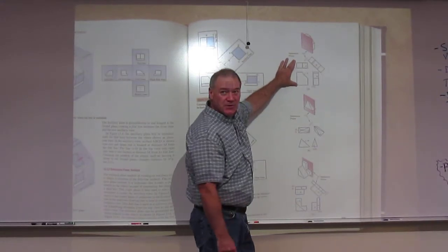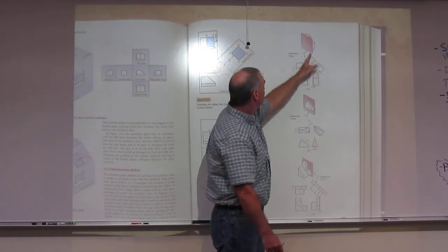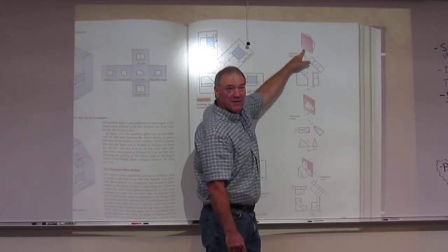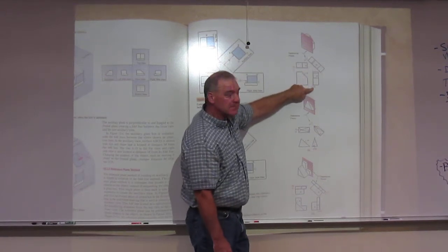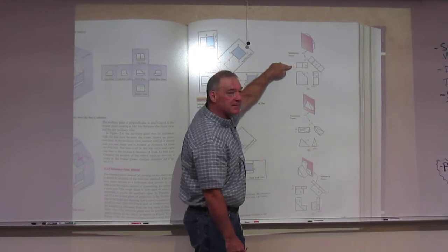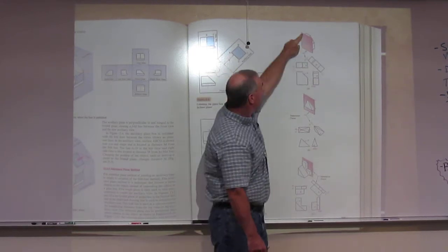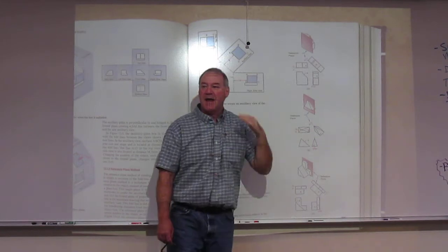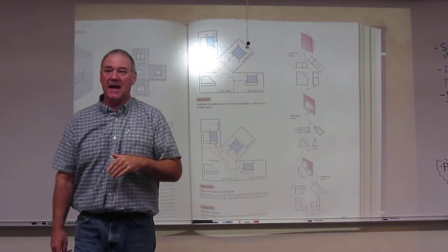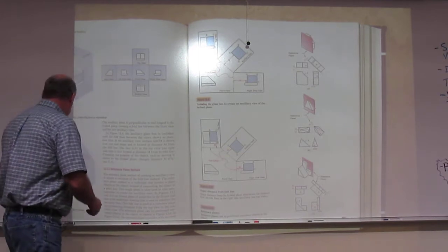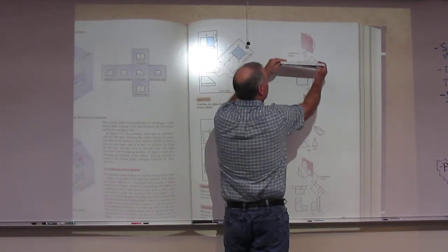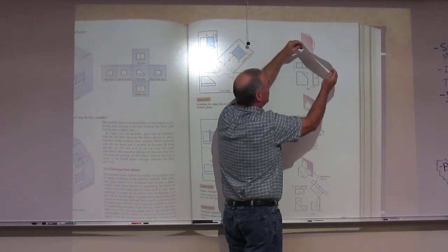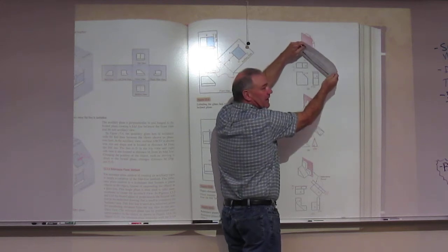Here you have a 3-view drawing on the reference plane. This little one they've got shown right here is going to be your reference plane. Now, you'll see this red line in the right side view, right here, and you see that same red line in the top view? That is this plane, or your reference plane, as an edge. You're seeing it as an edge there. So, in essence, think of it, that reference plane, we're just picking a plane, and we're going to see it on edge in this view, we're going to see it on edge in this view, so therefore in my auxiliary I have to see it on edge here.